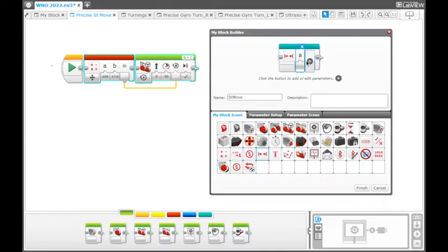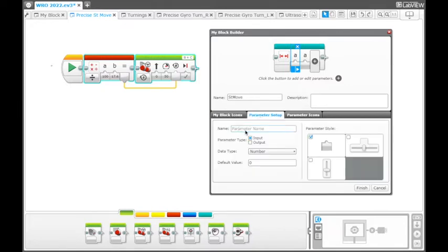So just click on plus option. You got one parameter here, and then another one you got here. So I'll click on the first parameter, and then if you go to the parameter setup on this, then you have to write the name for the parameter. So what we have to do here is the first parameter we want to put the distance. What is the distance between point A and point B? So here I'll write DIS, and this should be the input parameter.